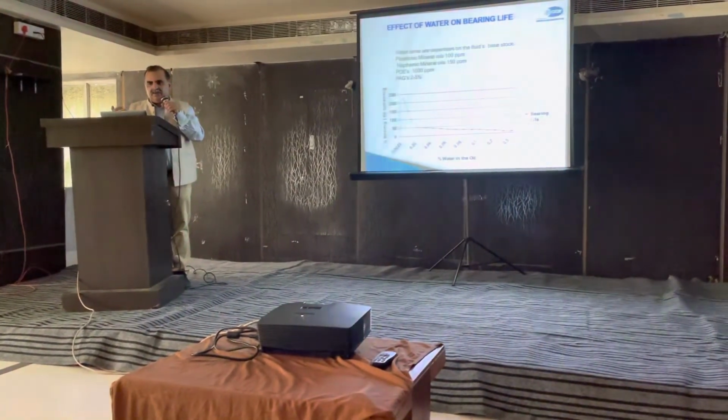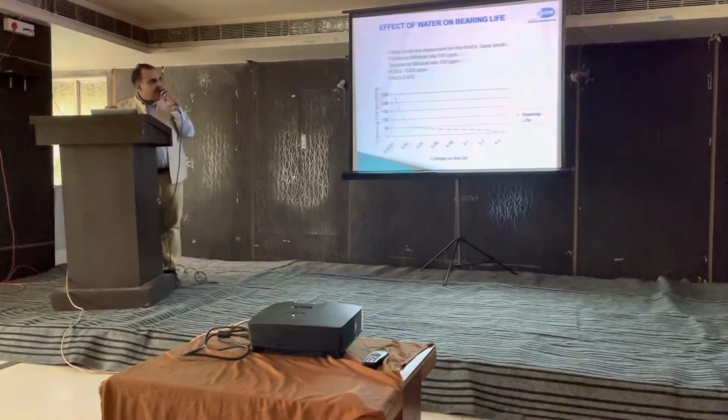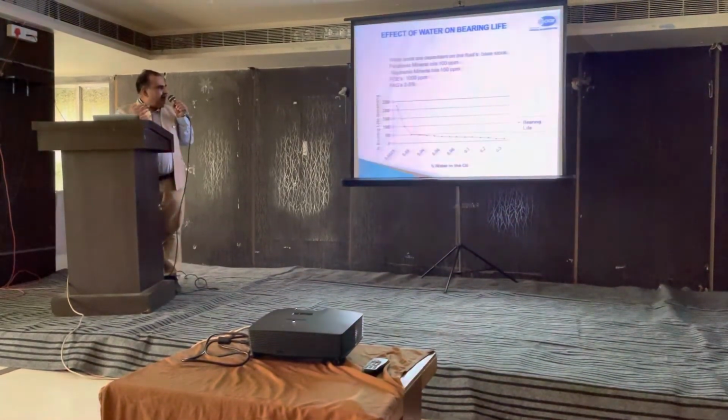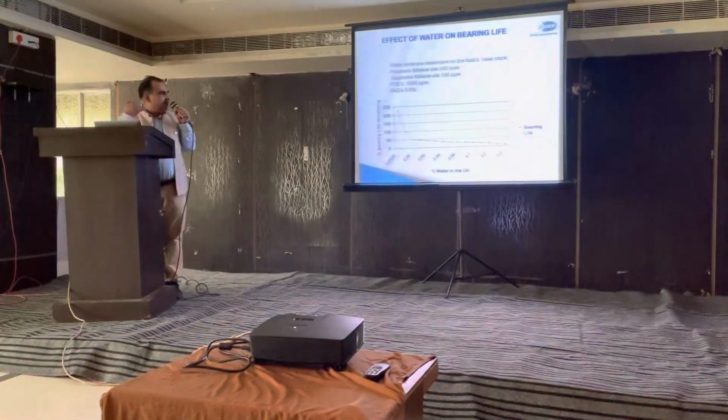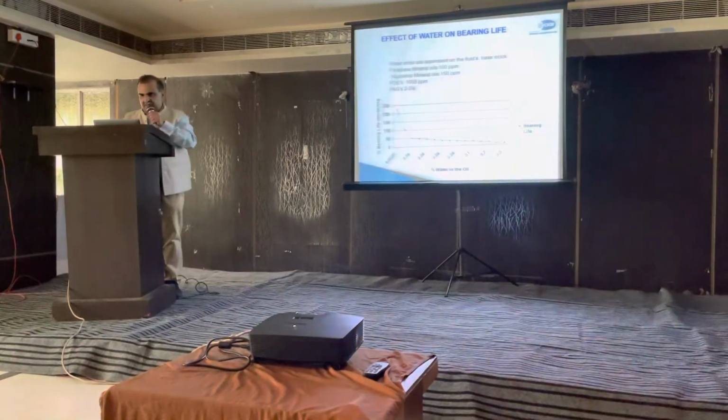The biggest effect will be on the bearing life of the compressors. Because of the water, the bearing life will keep on reducing, and your frequency of replacing bearings will be very high.